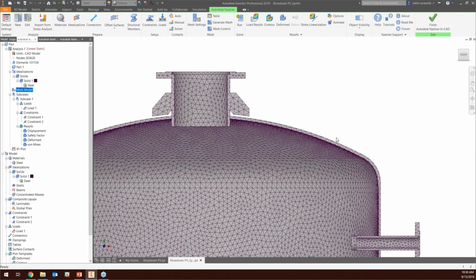You don't want to start running the most fine mesh possible. I made this mistake when I was learning all this stuff in college. I was like, oh, I'm just going to skip all of these simulation iterations. I'm just going to make 4 million elements, and I'm going to run this thing for 15 hours, and hopefully I get the right answer. We talked about this a couple of AVAs ago, right? There's a stage in which increasing the amount of elements is not going to increase the validity of your results. You're going to hit this plateau, and increasing the elements beyond that is going to give you reducing gains, right?